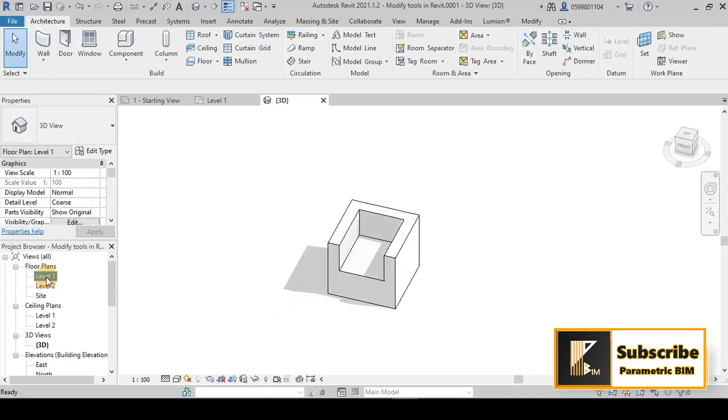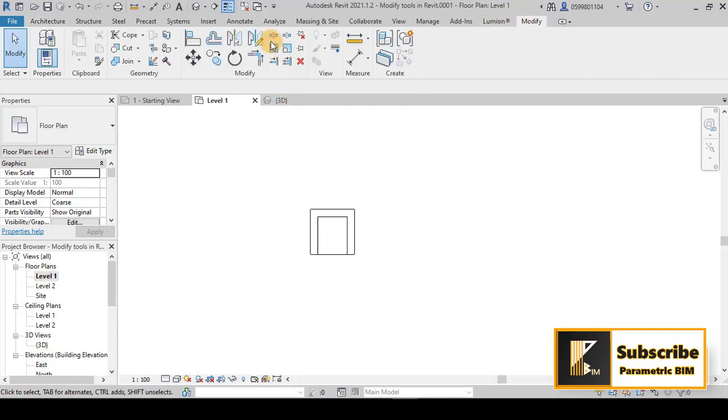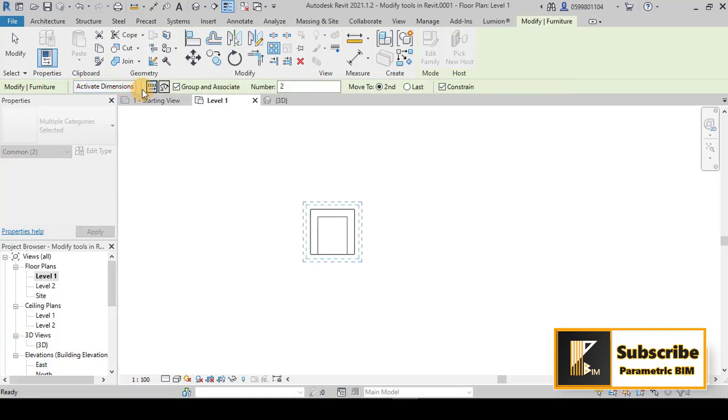and I will go to level 1. I will go to modify, modify tools, and then click array. I have now to choose the object that I want to array and then click enter. Once I click enter, I have to choose. As you see, I have linear array here and radial array here, and I have the number that I want to array and the movement type, and then I will go.